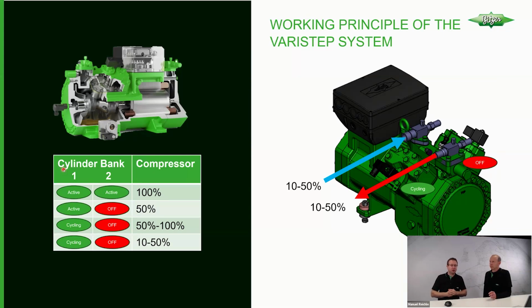But if the IQ module detects that the compressor gets too hot and needs cooling, it will override the signal and say, okay, I don't run the compressor with 10%, I run it with 20, and then it increases up the steps, step by step. With this measure, we force the rack controller to react.